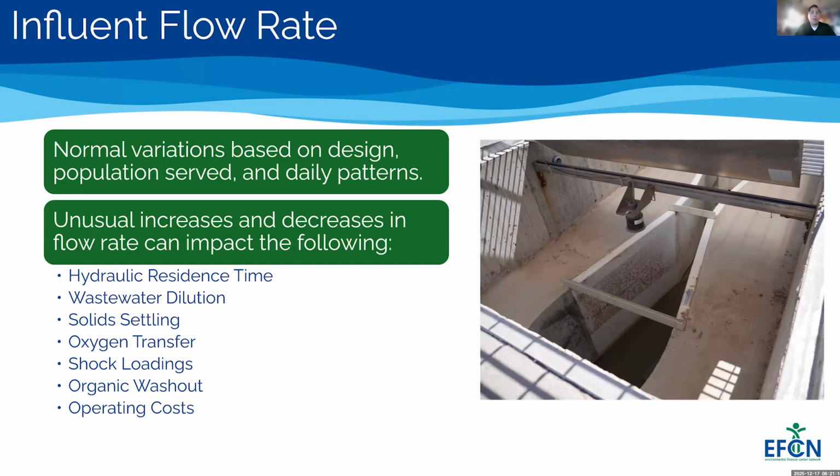Now, the hydraulic residence time influences the effectiveness of the biological treatment by providing microorganisms enough time to degrade the organic matter. A longer hydraulic residence time can lead to better treatment results by allowing microorganisms more time for the biodegradation of pollutants, but a high flow rate may lead to worse treatment results since wastewater may not be treated for the required amount of time.